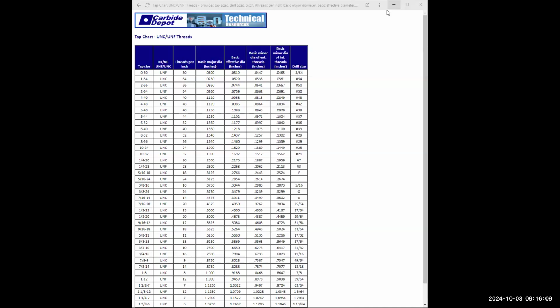Okay, we are making some good progress here. I'd like to try to get this wrapped up here in about 20 minutes. We're going to type in leader, enter, get close to the circle here. Let's type in near, enter, move it right there. That's near the circle. Click. What we have to do, hit F8. And we're going to come up with about right here.